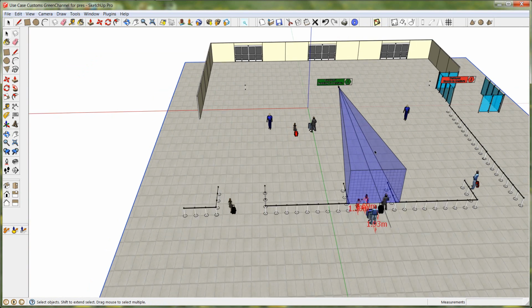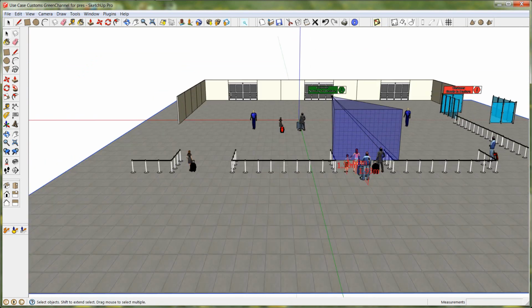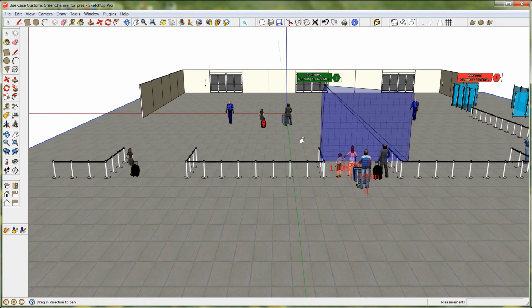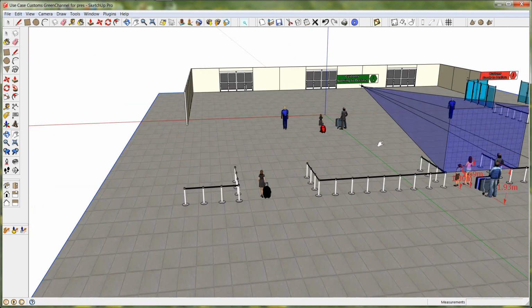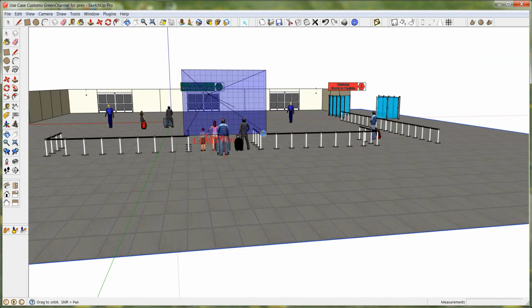But now we do have it in place, and now I'm going to zoom back out, and we're going to take a look at it, and we can see that, okay, this is the straight 0-degree tilt on the camera, with the camera up at approximately 8 feet, looking straight out. And what we see there is that there is a significant gap between the lower edge of the field of view and the floor, which of course is not the way the image should be placed, right? We would actually tilt the camera down, and we will do that in a moment here.